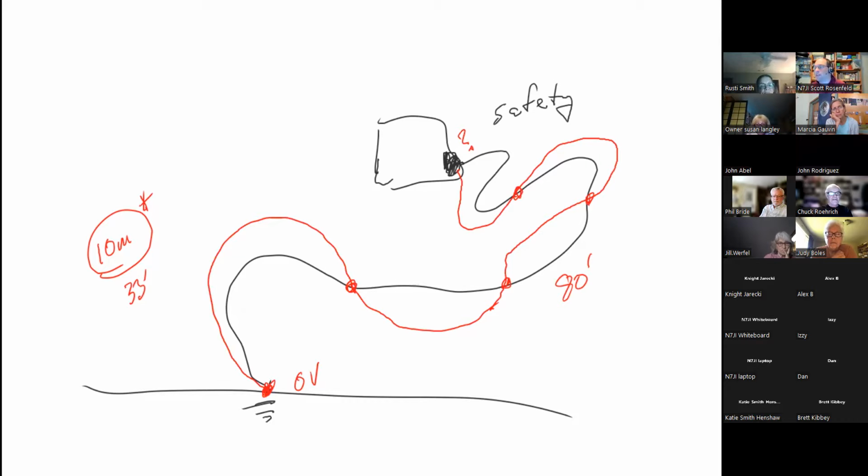Is there any guarantee that that's 0 volts? No. There's not. And in fact, depending on the band that you're on, the frequency that you're using, that actually can change, which basically means you lean in to touch your microphone, and what happens? This is suddenly at 100 volts. Get zapped. And I have had that happen, where I leaned forward into the microphone and got a zap on my lip as soon as I started transmitting. And that's because safety ground is not equal to RF ground.